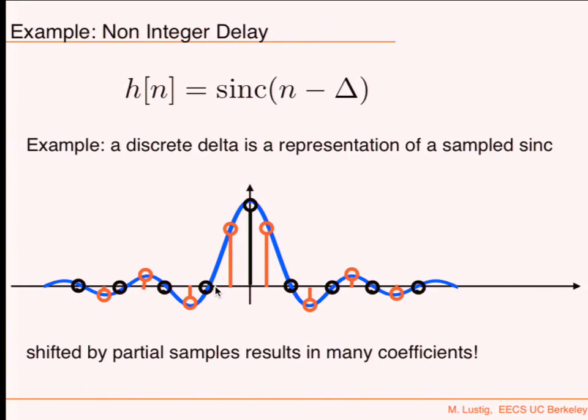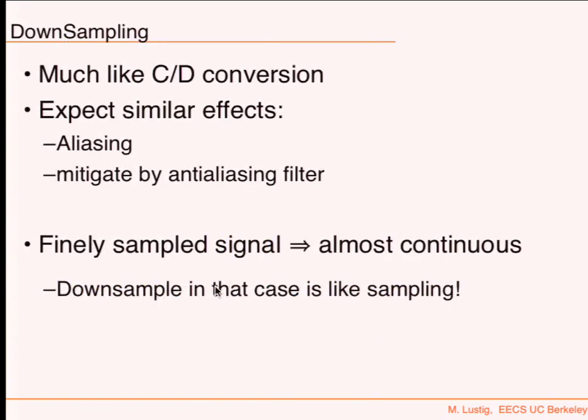The first thing that we're going to do is downsampling. Where does this come up? You're going to see it in Lab 2. You're going to sample at 240 kilohertz. That's what your SDR is going to give you. You're going to do all sorts of processing. You're going to get audio at the end at 240 kilohertz. Now try to give your computer samples at 240 kilohertz to play. I bet it is going to be upset. Really upset. So upset that it's not going to play.